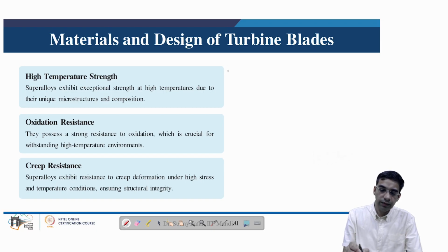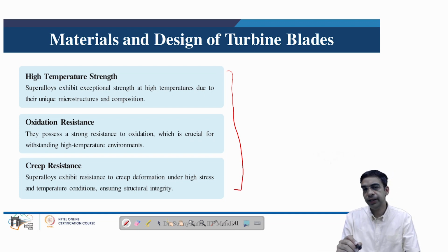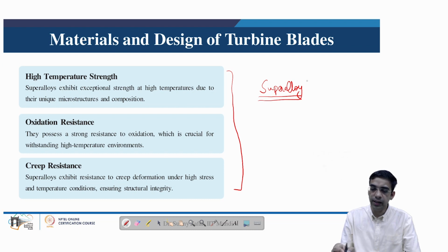So to find a material which has all these properties, we have to look back at the material charts that we have seen. Generally the metallic alloys are suitable for such applications, but what happens in most of the metallic alloys is a sudden loss of strength and resistance to creep with increasing temperature. So to overcome that limitation, instead of alloys, superalloy materials are used in making the gas turbine blades. So we understand that material selection for gas turbine blades will revolve around the discussion of superalloys.